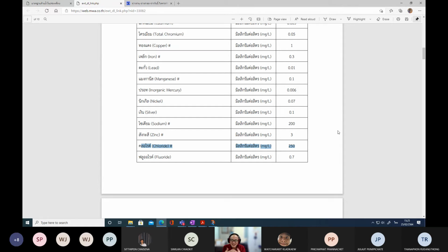As it is a conservative substance, whatever is coming in is just going out. So if it's coming in at 250, it will leave the treatment plant with approximately the same concentration, maybe 250 or 260. So it's more or less the same influent and effluent. I'm talking about the water treatment plant. As I told you, 250 doesn't pose any negative impact to human health, but the consumers maybe don't like it if the tapped water contains chloride higher than 250 because it gives a salty taste. So I'm talking about the chloride, okay?